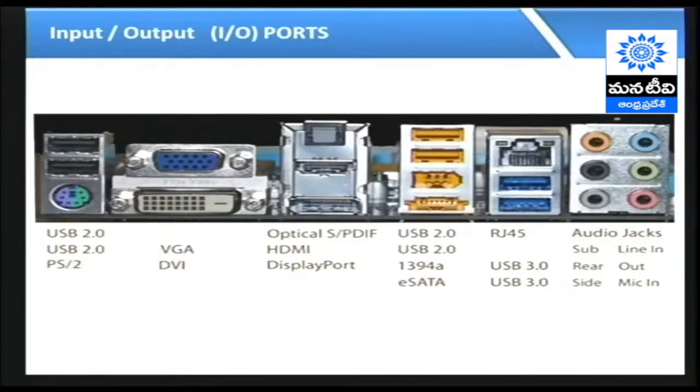Look at the screen. Here on the screen you can identify one port, one interface of the motherboard, that is the input output port USB 2.0. USB stands for Universal Serial Bus. One more port is there, under USB 2.0, you can identify a violet and blue color combination port. It is a 6-pin DIN connector. That DIN connector is generally called PS/2. This PS/2 connector is generally used to connect old type keyboards and mouses.